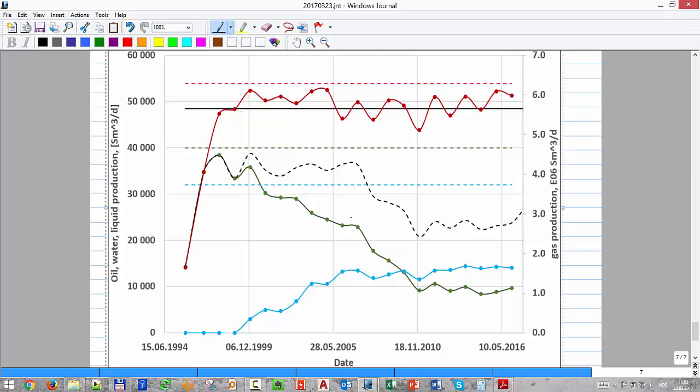So what I'm saying is that you use those limits in your production calculations, and they are really going to tell you when you have to choke. Because for example, in many other fields, what happens is that you hit the maximum water processing capacity, and then I have to choke. I have no other choice. Okay, I have to reduce all rates to bring that line back to the limit, because I cannot process more.